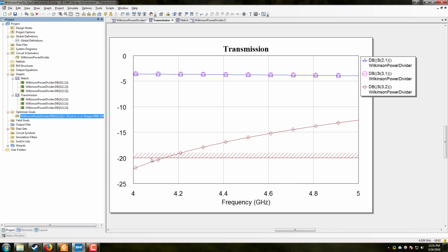So in the graph, you'll see this new line with these dashes along the line. The dashes show basically the upper boundary of that goal. So basically we're saying that from -20 down is our goal. If they were flipped the other way, we're basically saying from -20 up. If it just shows kind of like a thick line with dashes on both sides, we're basically just trying to match the value itself exactly.